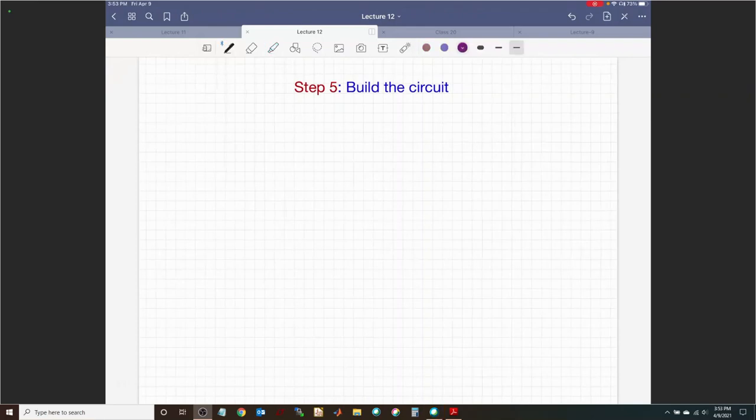So let's start talking about how you build this design. This is how I do it. I first draw my 3 flip-flops in the same sequence, from most significant down to least significant. That's just a personal preference. So this is my first flip-flop here, the second one here, and the third one here.